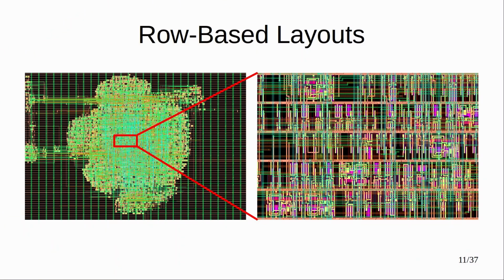And when you do this place and route step, you get a vector graphic representation, and when you look at this, it's very hard to understand what it should be. For instance, the picture on the right is maybe 6,000 cells together with wires. When you zoom in, you start seeing a bit more structure. You recognize that things are arranged in rows. You see some patterns that seem to be repeating, and those are the logic cells.